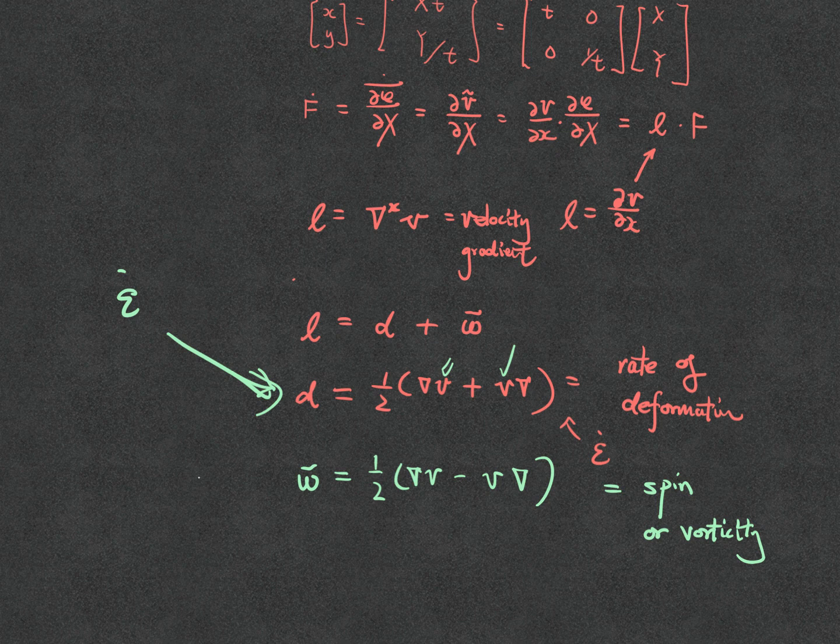But W is important, in the sense that when you write the constitutive law, you don't want to directly use the velocity gradient, because then the spin would enter into the constitutive model, and that is not going to work. Sorry about that. I'm about to get to the stress and defining everything, and once we get there, we can write the large deformation constitutive law.